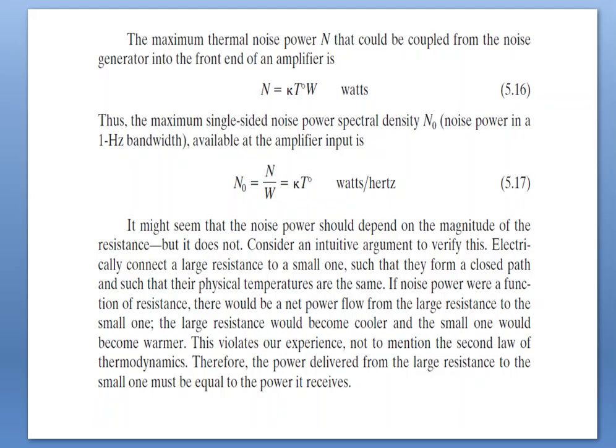It might seem the noise power should depend on the magnitude of the resistance, but it does not. Consider an argument to verify this. Electrically connect a large resistance to a small one such that they form a closed path and their physical temperatures are the same. If the noise power were a function of resistance, there would be a net power flow from the large resistance to the small resistance.